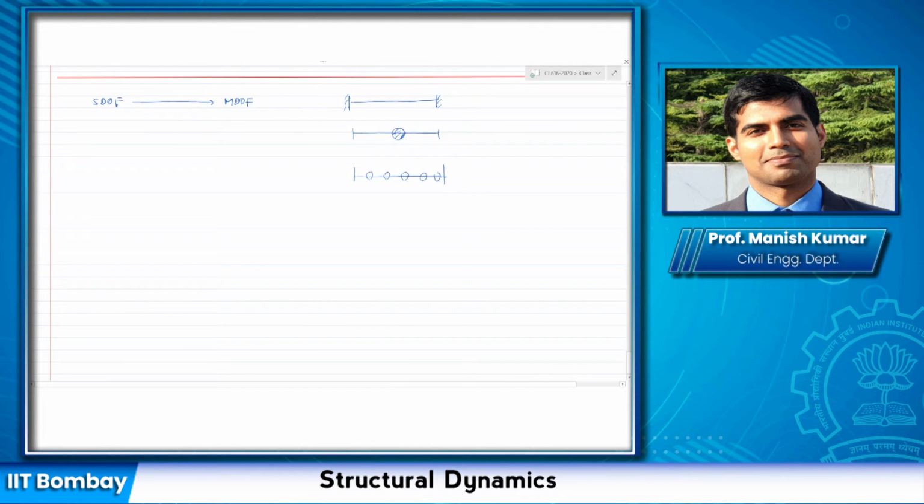And then we said that before going into this multi-degree of freedom system, these are the two representations. Is there a way through which we can analyze a continuous system without having to deal with multi-degrees of freedom? And for that, we defined generalized SDOF system. In a generalized SDOF system, we basically said that if we have any structure, we took a very simple example of, let us say, simply supported beam or a cantilever beam.